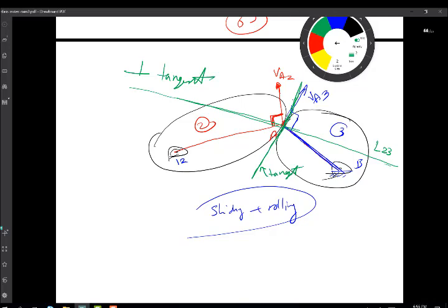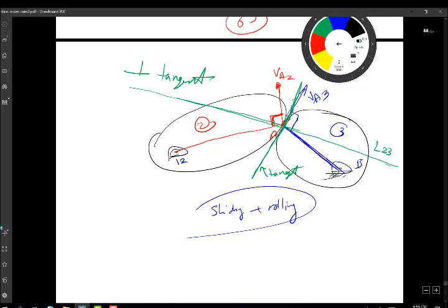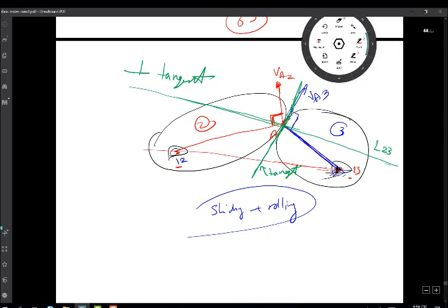And in this case, of course, you can tell straight away if you want another locus for the point of common velocity. This example is as simple as applying Kennedy's theorem. This is point 13 here. Okay, this is 13. So this is point 13, and this is point 12. The common number is 1. The missing numbers are 2, 3. So I can just connect those together, and this will give me another locus for 2, 3. So when those two lines intersect, I'll get 2, 3.